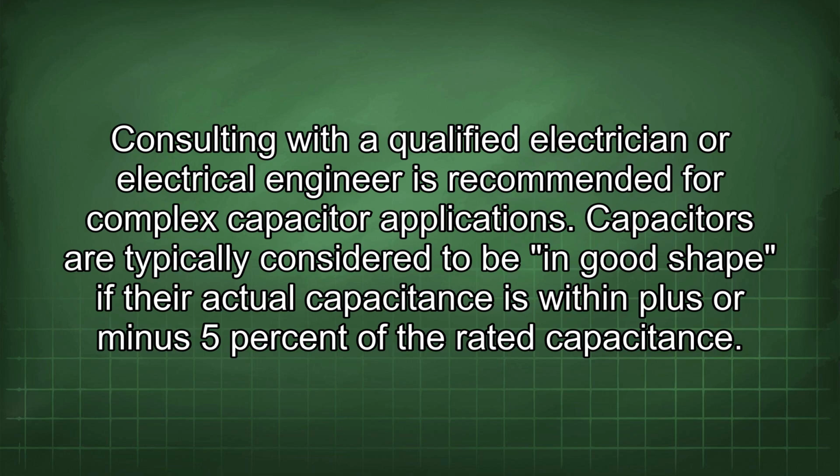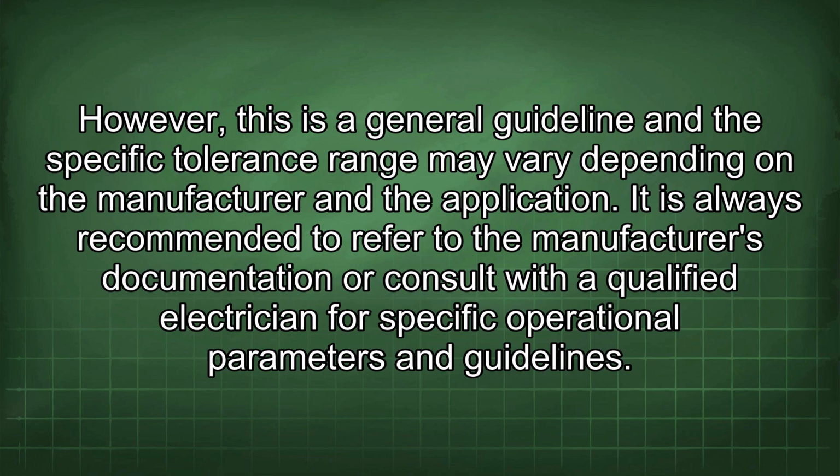Capacitors are typically considered to be in good shape if their actual capacitance is within plus or minus 5% of the rated capacitance. However, this is a general guideline, and the specific tolerance range may vary depending on the manufacturer and the application. It is always recommended to refer to the manufacturer's documentation or consult with a qualified electrician for specific operational parameters and guidelines.